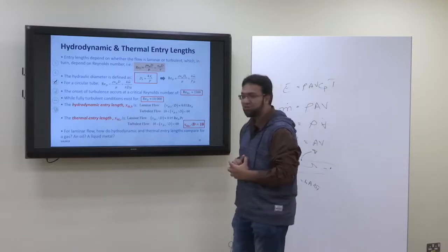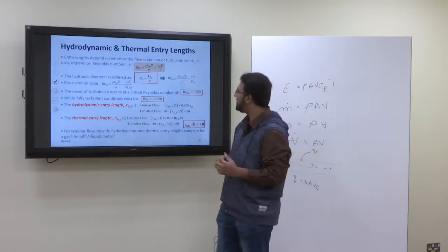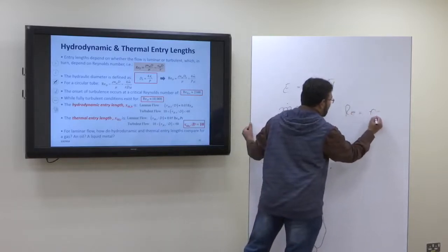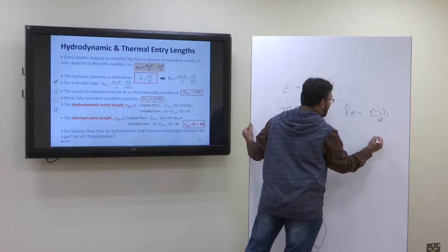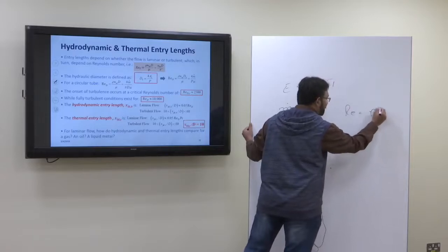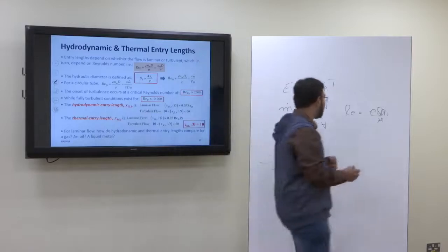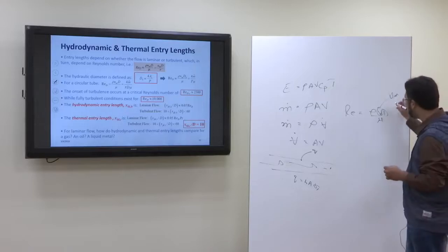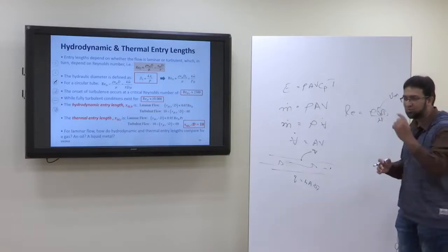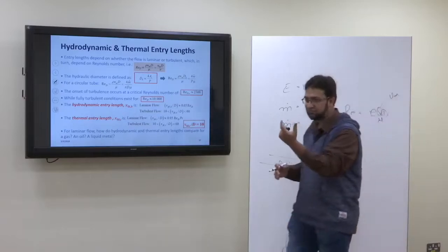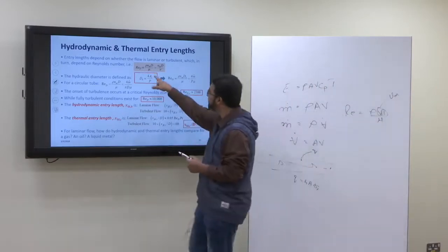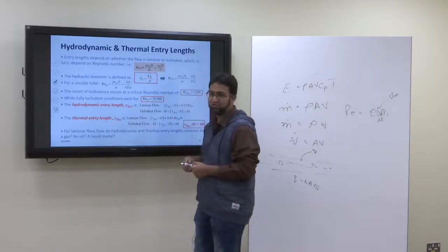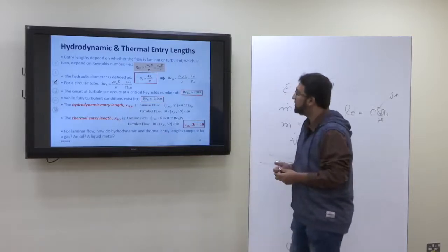Okay. Reynolds number. Reynolds number is what? Rho Vd upon mu, right? We're talking about this velocity here, so this velocity should be the mean velocity. Sometimes they write velocity as V, sometimes as u, but you can understand it means velocity. Here they wrote it as u, the mean velocity. So that will give you the Reynolds number. We'll talk about the diameter.